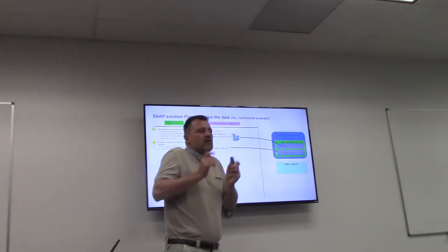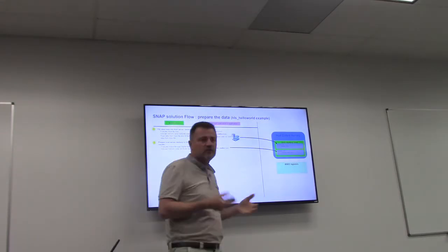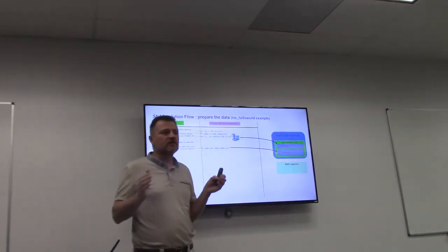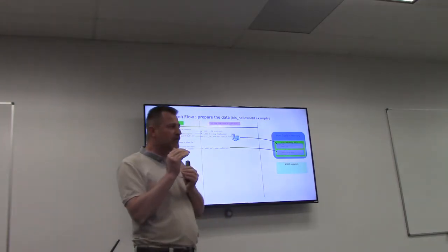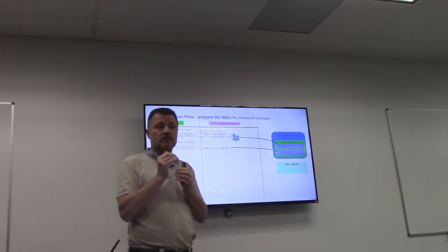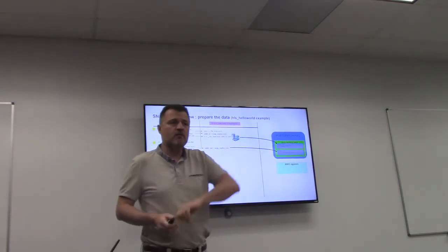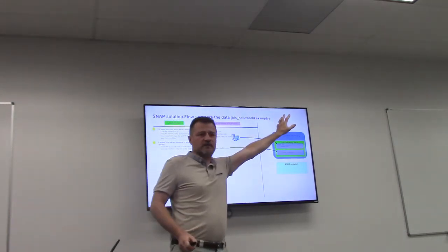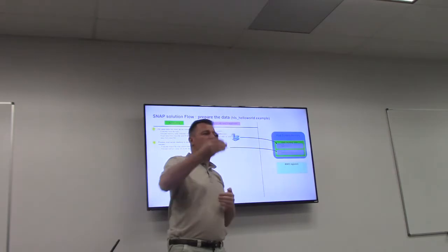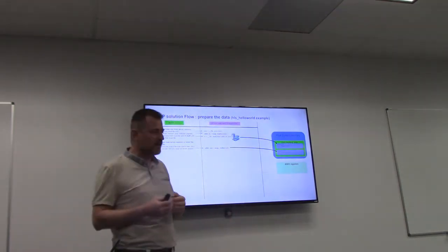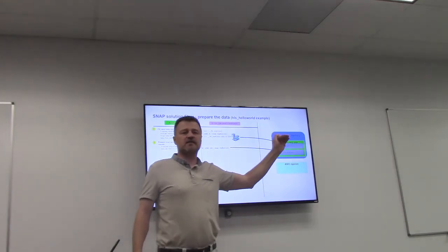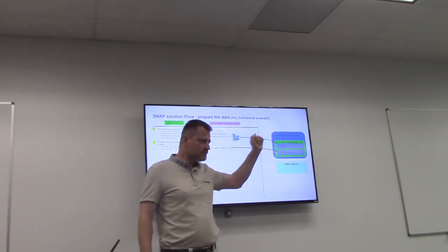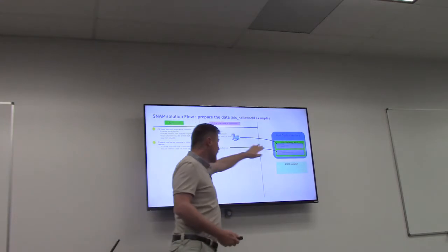So when we call the action in the FPGA, we have voluntarily reduced the exchange to a very small number of bytes. If you want to exchange more, put everything into the memory and give an address for that. Agree with the action on a protocol that says, okay, at this address in the memory, you will find all the necessary things that you require. So we have a very small exchange.